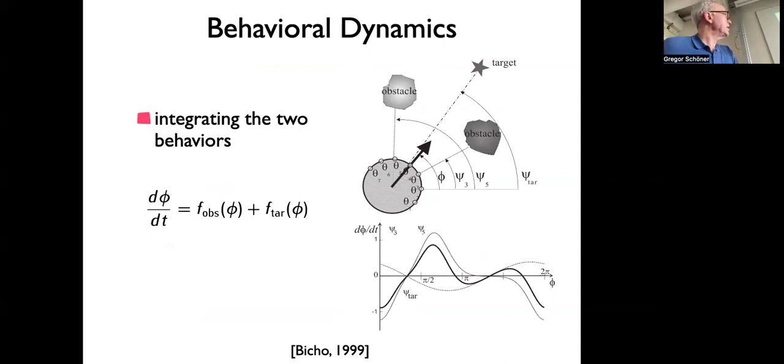The target acquisition is actually unchanged in these examples. The book chapter just assumes that we know where the target is. In many of the applications, the target was fixed by dead reckoning. That is, we assumed there was some initial position, we assumed there's a coordinate frame, and we programmed into the robot that the target is at these coordinates, in X, Y, from the world axis, from its heading. And then the vehicle kept track of where it is by adding up the commands to the wheels, essentially phi dot, right? You also need the speed, of course, the forward speed. And you just add that up.